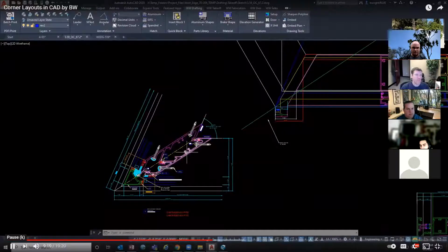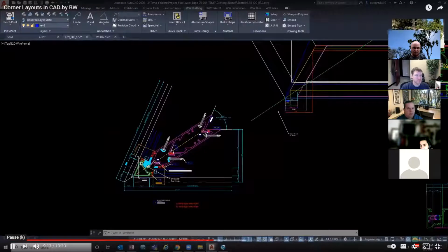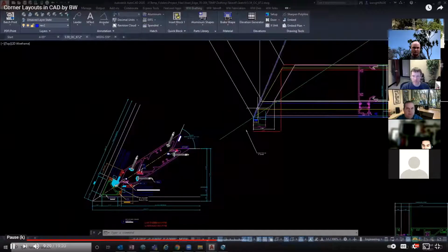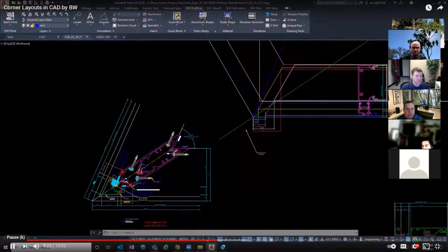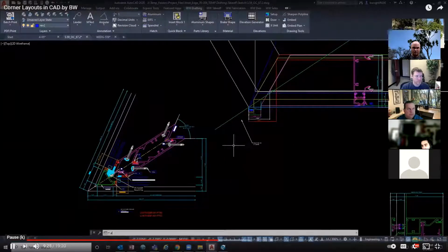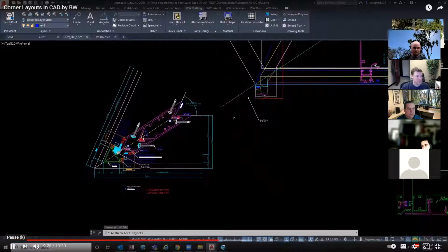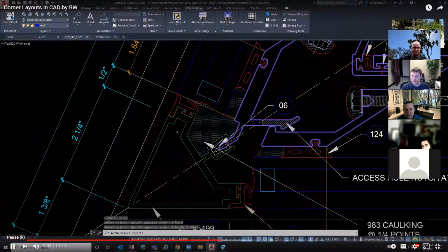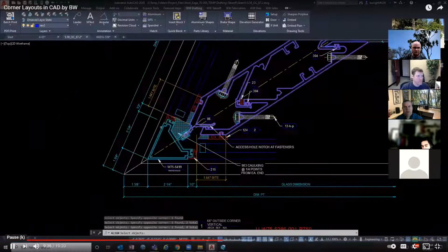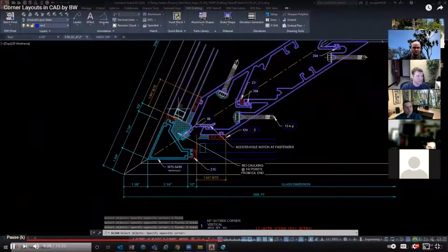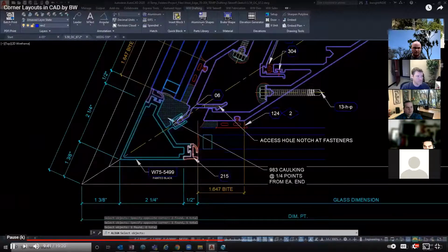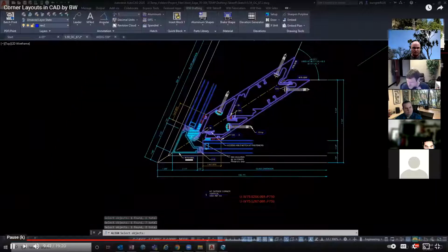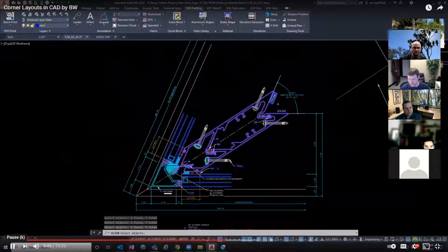I want, which is the vertical mullions, the face cover, the glass, and just the two pieces of gasket here in the front. And I'll align that based on this center point. So I use the align command. Select my parts, which is my two verticals, my vertical face stop, glass and gasket on both sides. And I'll bring the part numbers with me as well.